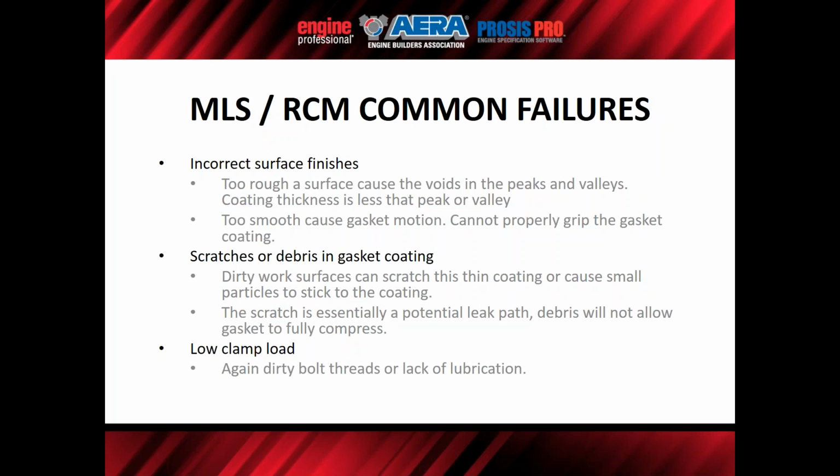So when you're doing these installations, make sure the work surface that you have is clean. Take the gasket kit, open it up, leave the stuff right in the kit if you need to. But if you're going to take the gaskets out of the actual kit, make sure where you're putting it is clean and you don't have any issues with scratching or picking up debris. Low clamp load again: dirty bolts don't provide enough clamp load. Lubrication, you need that to pick up more load by lowering the coefficient of friction. So take care of those things.